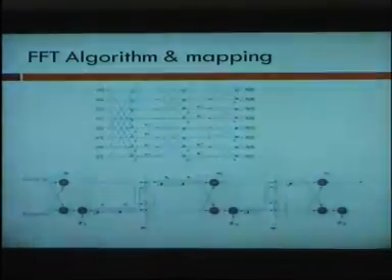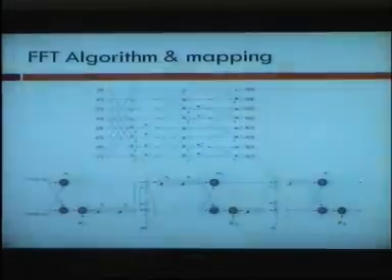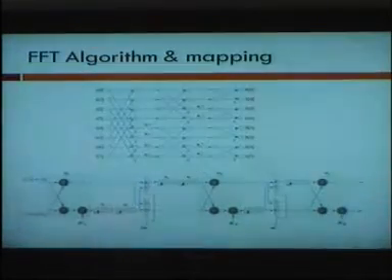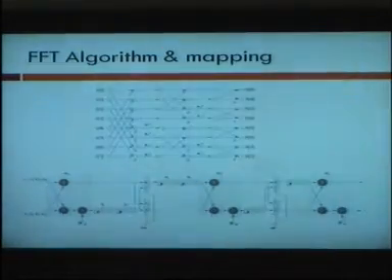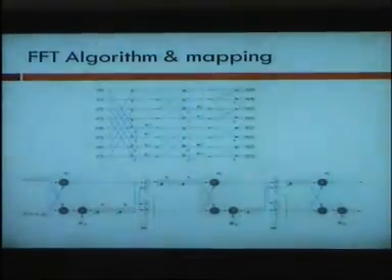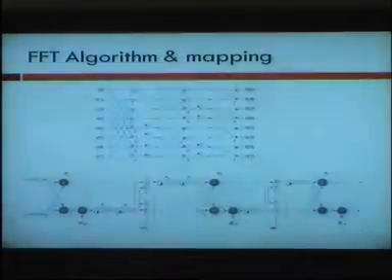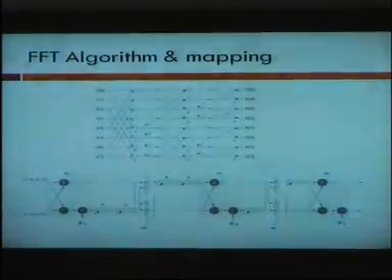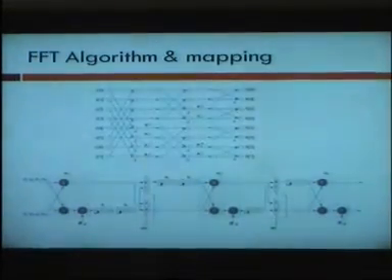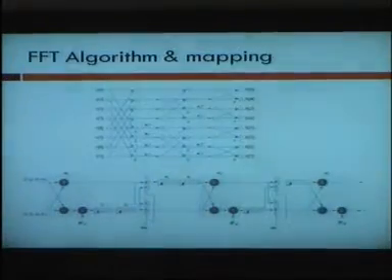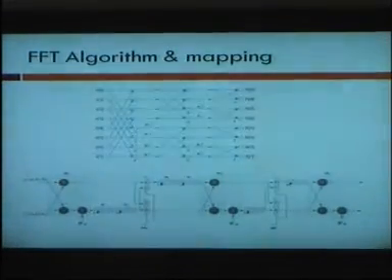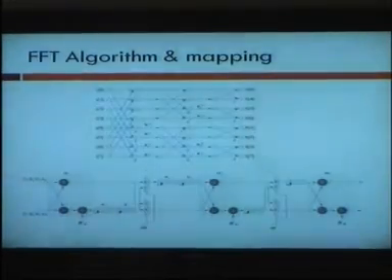Where there is a multiplication, a multiplier. Many people try to do this. If you ask somebody to design, usually this will be their first preference because it's very easy to design, but disastrous as far as the area or the resources are concerned, because mostly you don't need your algorithm to work in parallel. You don't need to do everything in parallel because you don't have those types of requirements. So it's very rare that you need to do things like this.